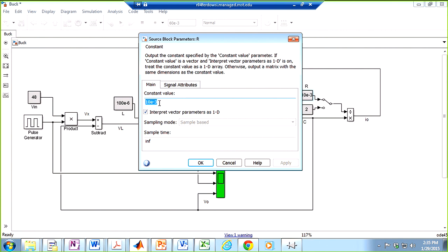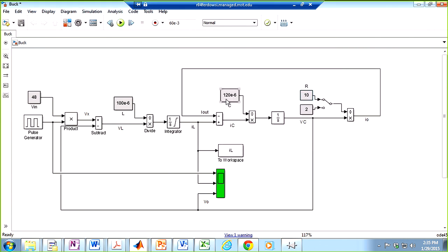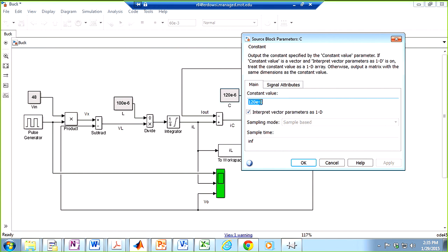So remember, the size of the capacitor is in charge of establishing a constant output voltage. So if our capacitor is too small, we are violating that assumption. So let's see what happens if we violate that assumption. Let me bring our load to a normal load of, for instance, 10, and then pick a very small capacitor, like in a nano range, like 1,000 times smaller.